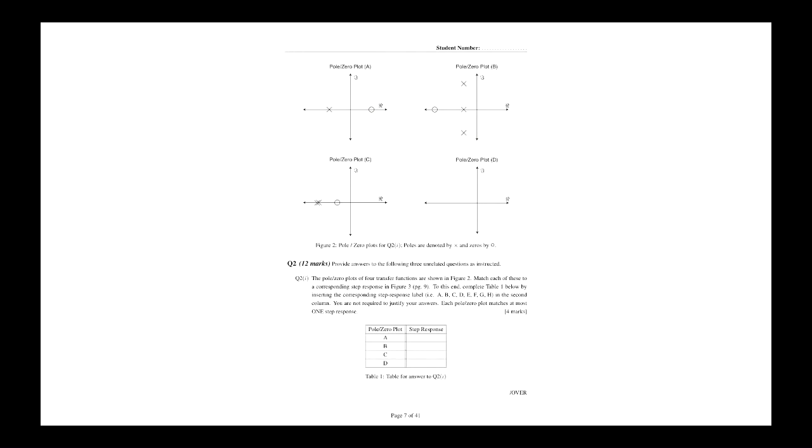When you have a right half plane zero, you might get some undershoot, right? And undershoot's about moving in the opposite direction to where you'll end up. And from a pole zero plot, you can't tell the sign of the DC gain. So the response to a positive step in might go to a negative final value, if the DC gain is -1.